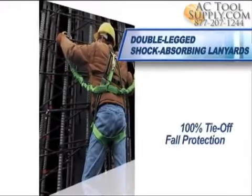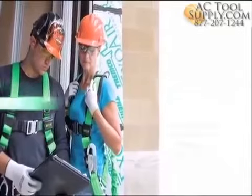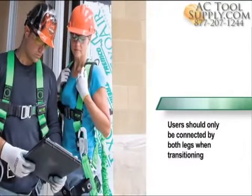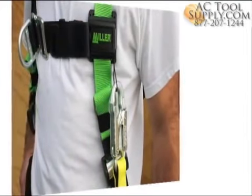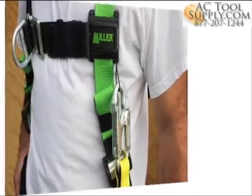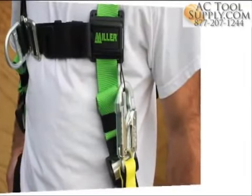If one leg is not used, it should be connected to a pull-free lanyard ring on the harness and never be attached to any permanent fixture on a harness such as a side D-ring. All Miller brand harnesses include pull-free lanyard rings, designed for storing a lanyard or extra lanyard leg when not in use.